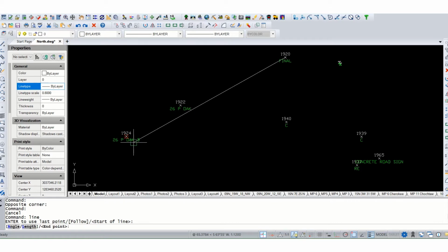I'm standing out in the open, so I have a good sky and a good fix, and my GNSS receiver has a tilt function, so I was able to set the tip of the pole at the center of the tree, 90 degrees perpendicular to the section corner, and get a good fixed shot there as well. We checked all these with tape, and we were plus or minus about 1/10.